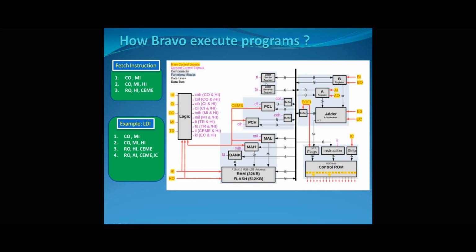Now, we talked about the UART RX and TX modules. Both of them are either reading from or writing to our bus. We also talked about the program counter, which has a high byte and a low byte, and I've talked about all of these modules in detail in their related videos. If you remember from the program counter, we had the high byte and low byte concept, because our program counter is 16-bit and our bus is only 8-bit, so we needed two different clock cycles to put all the content of the program counter on the bus.